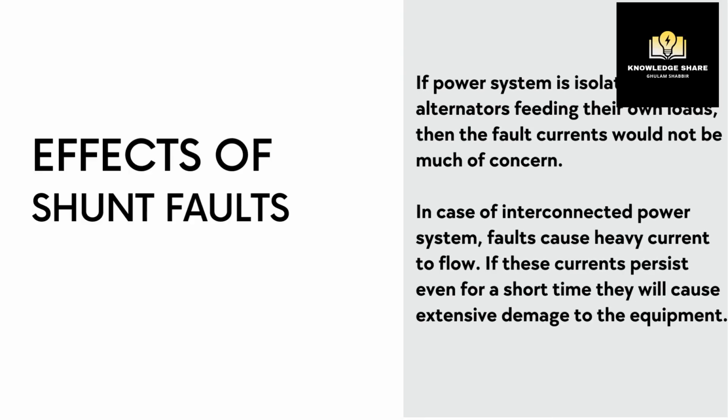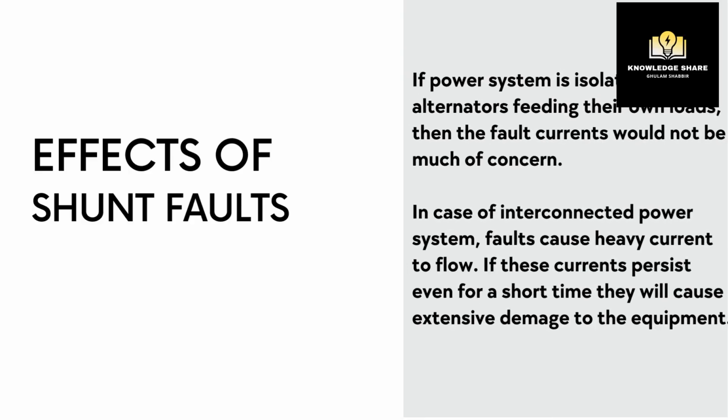Effect of the shunt faults: if the power system is isolated alternators feeding their own loads, then the fault current would not be much of a concern. In case we have an interconnected power system, faults cause heavy currents to flow. If these currents persist even for a short time, they will cause extensive damage to the equipment.